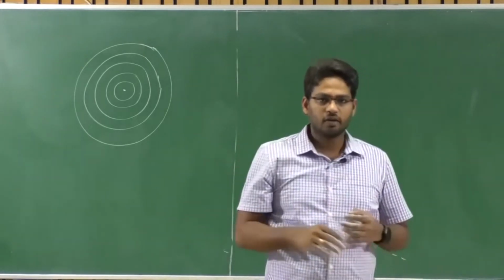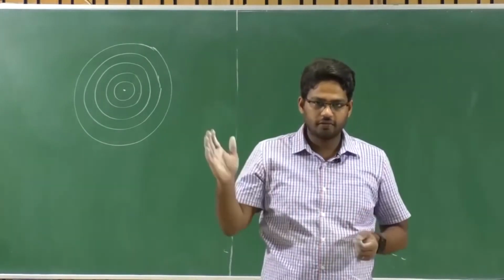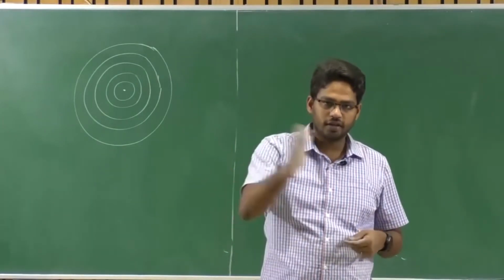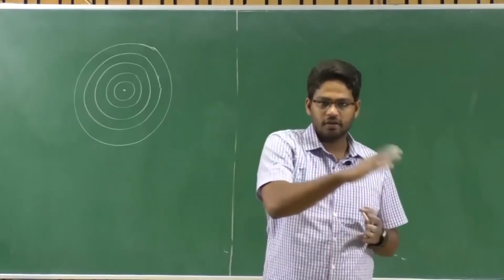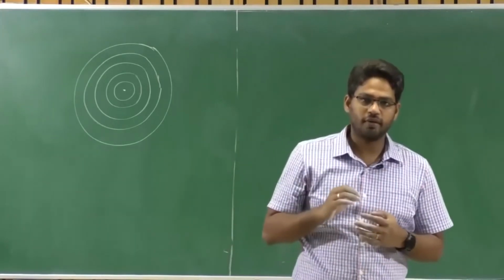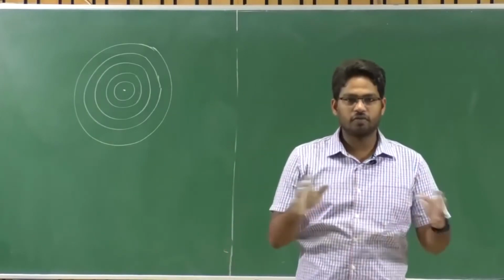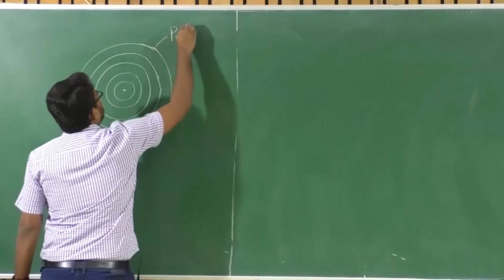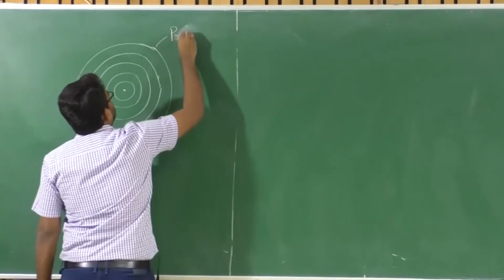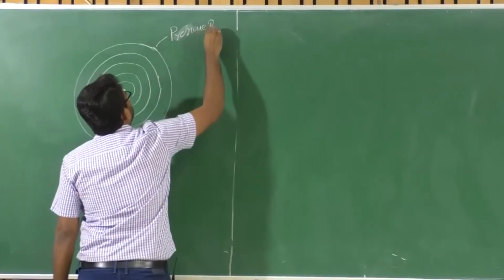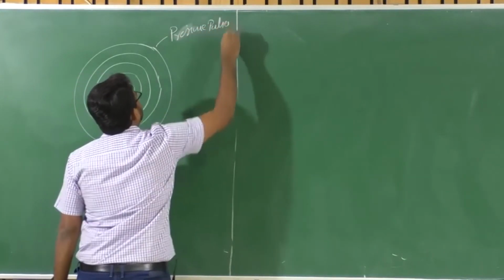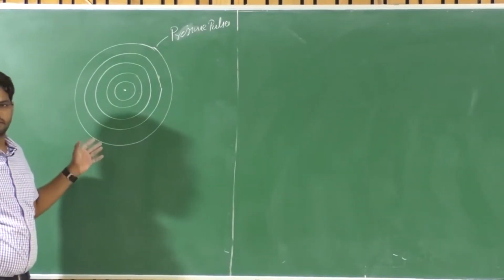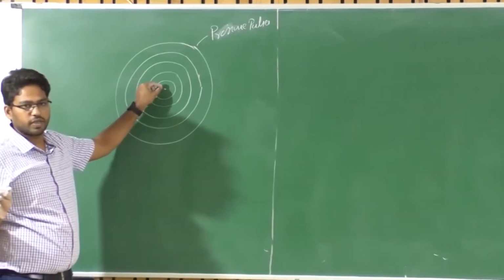If I just push air like this, or if I blow air, right? If I disturb the current state of this particular ambient condition, then we can assume that disturbance will create a local pressure difference, which in turn travels with the velocity of sound in the form of pressure pulses. So this particular disturbance that travels is known as pressure pulses. These are the pressure pulses that propagate the disturbance from the given location where we have created it.